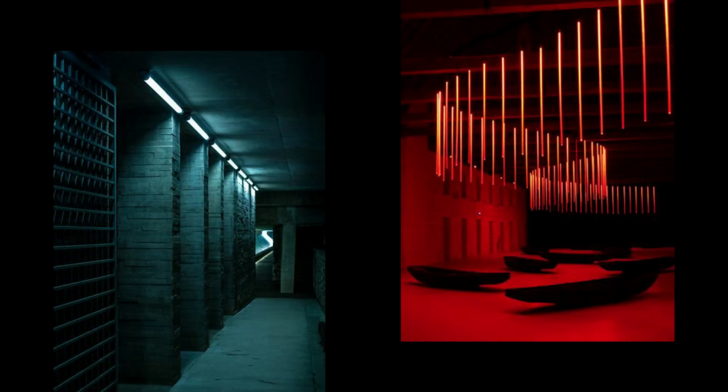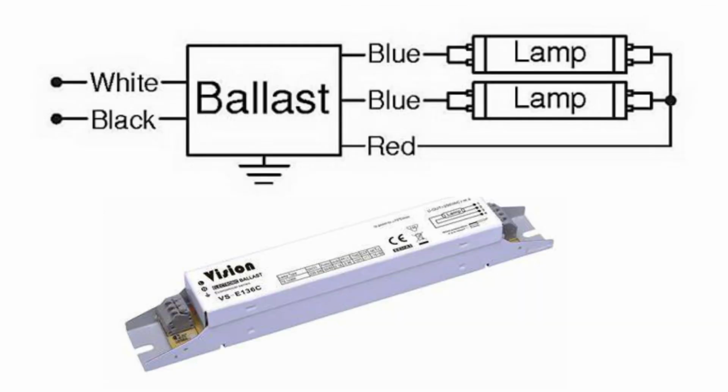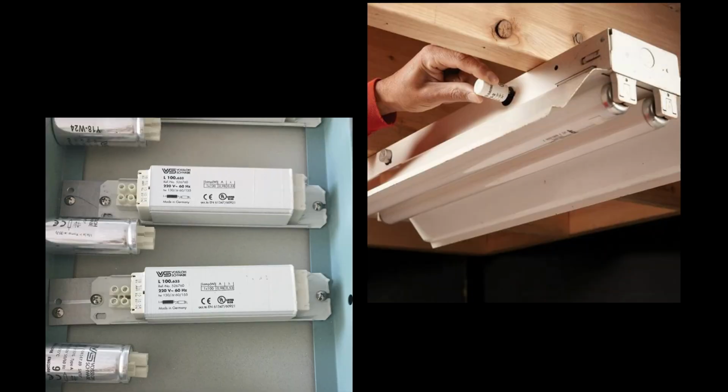the visible light range. A ballast is required for all fluorescent light sources. The ballast serves for supplying the high voltage necessary to start the arc and limiting the current in the arc after it is formed. For the operation of some fluorescent tubes, an automatic switch known as a starter is required in addition to the normal wall switch.